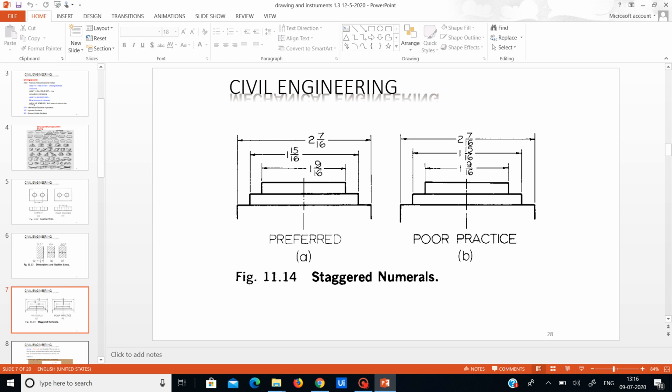When the step by step program is going on, like rectangular one upon the other, and also when you go for circles, when there are 3-4 circles, then you have to give the dimensions very perfectly. The diameters of the circles must be given one after the other, one upwards, one downwards, all of them on the same side.